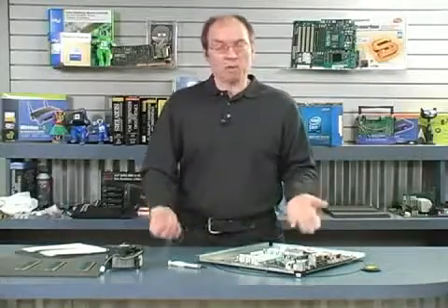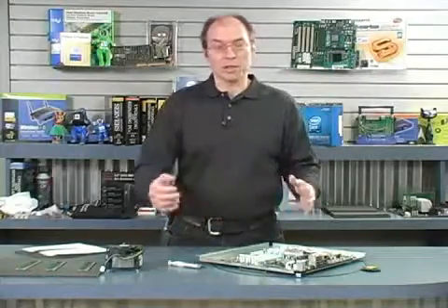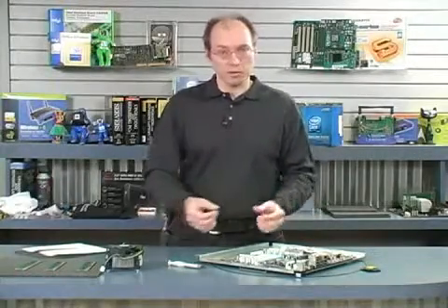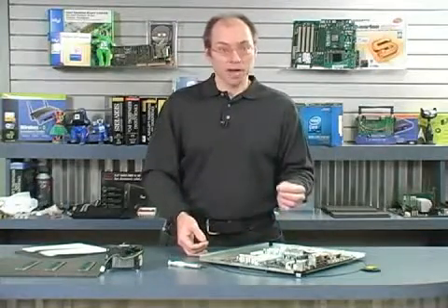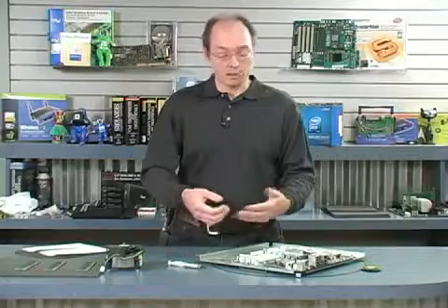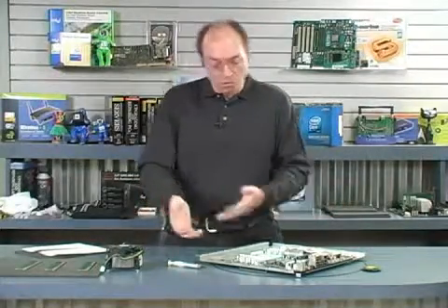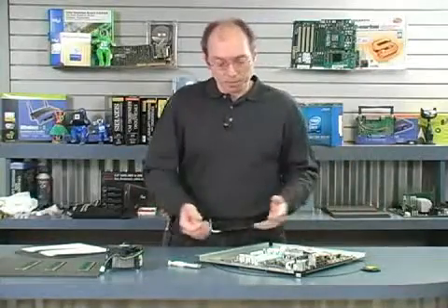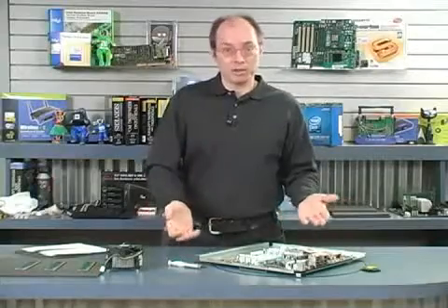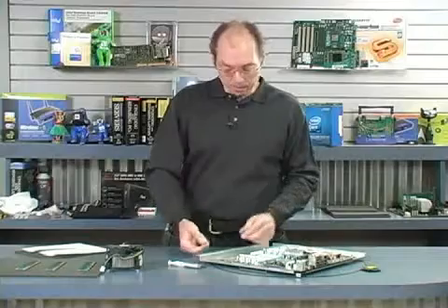Either one performs pretty much the same thermally. In fact, I've seen numerous tests of hundreds of different types of thermal interface material, and rarely see more than a 1 degree difference in the actual operating temperature of the processor, depending upon the different materials. It doesn't really matter. People always ask me, what kind do you recommend? Do you recommend the Arctic Silver or something else? I recommend whatever you have. Just use whatever you have. As long as it's properly applied, it's going to work properly.